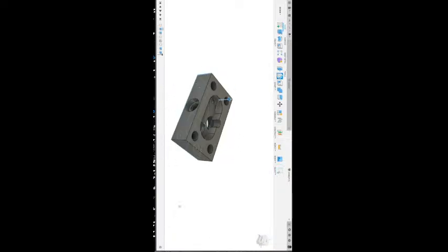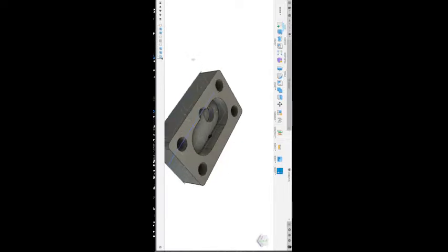There are 2 ways. You can go back to the sketch and do it, or you can click fillet, F for fillet, select all the 4 edges and hit 1. It's going to be 1. Boom, that's it. We are done with the model.